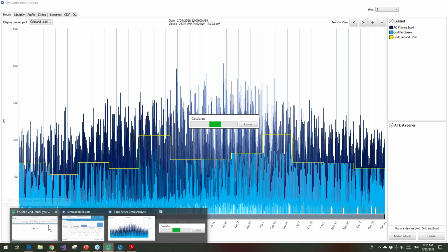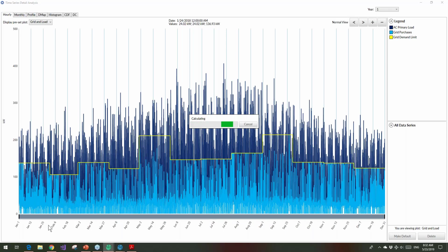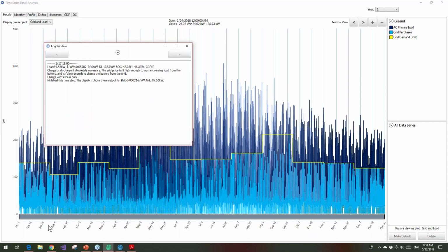difference between the two products. Also, HOMER Grid's utility component is very complex. So you can set all kinds of different tariffs, like ratchet rates, contracted demand, all the things that come with being attached to a very complicated utility. HOMER Grid covers that. HOMER Pro does have some grid-connected modeling capabilities, but they are much more limited in the tariff structure that you can build up.